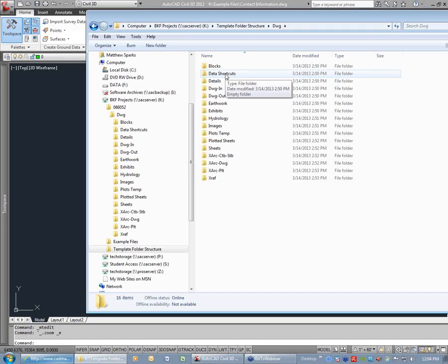And the theory here is, why would you want to share between drawings when you can just X-reference and see that? So you want to ask yourself, do I need to share the actual Civil 3D data, or do I just need to see it for a sheet layout? If you're doing grading, or corridors, or some of the design side, you really have to have access to that data so you can daylight to it, extract information from it, or label the actual object. AutoCAD doesn't do that for you through X-references. So you have to use a combination of X-references and data shortcuts.